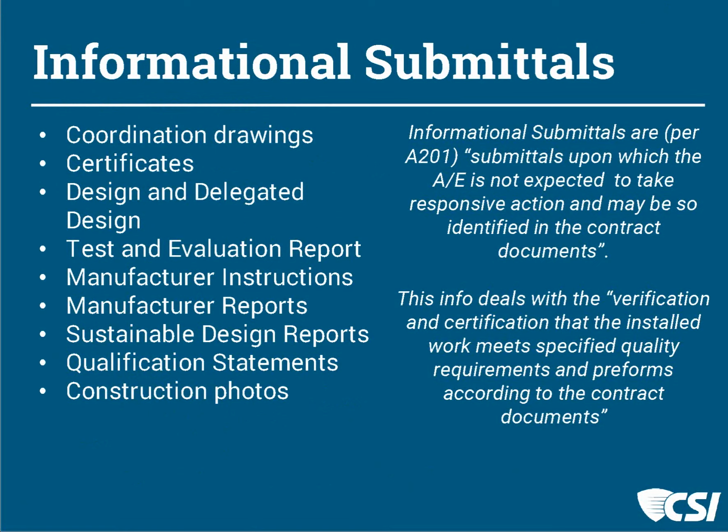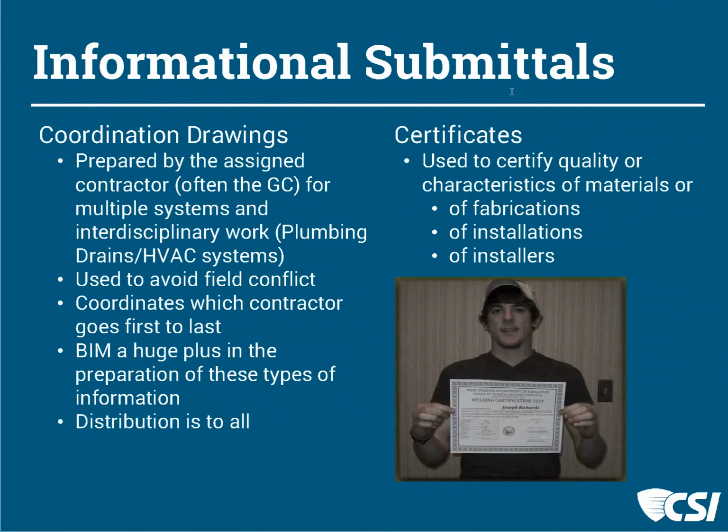So let's look at the first one, and maybe I'll answer that question over this series of slides. So if you look at the next one, Matthew, coordination drawings, why would we want to see those? Well, we want to see that there's an assignment of who's on first, and whether the sequence has been thought through by the general contractor to avoid conflict, so that the pieces of the project that need to be installed before others have been thought through.